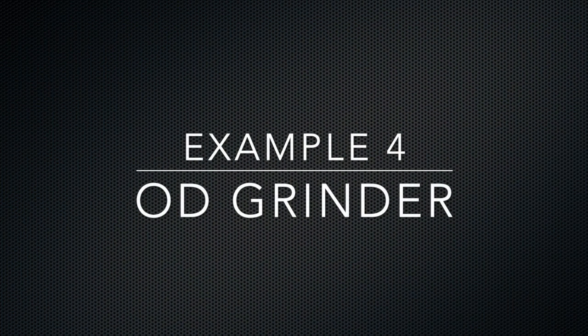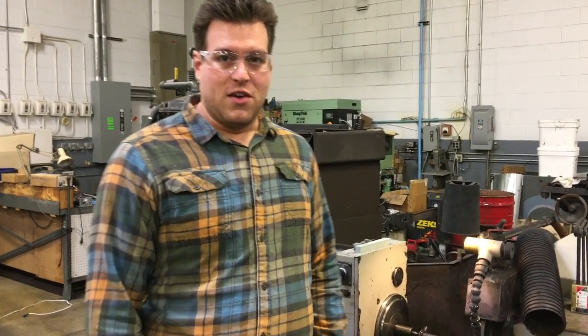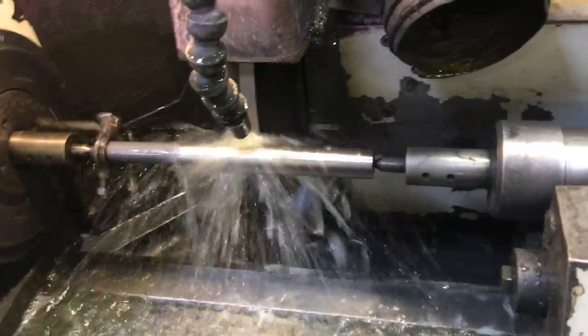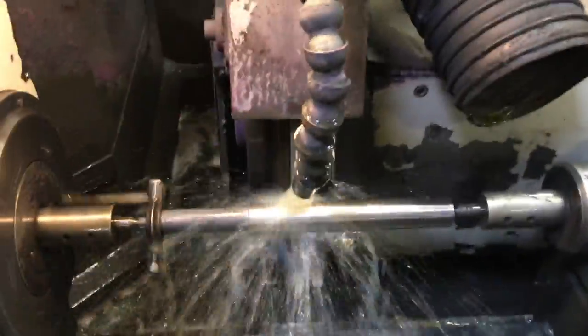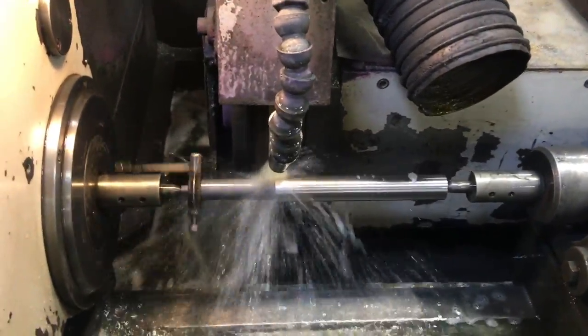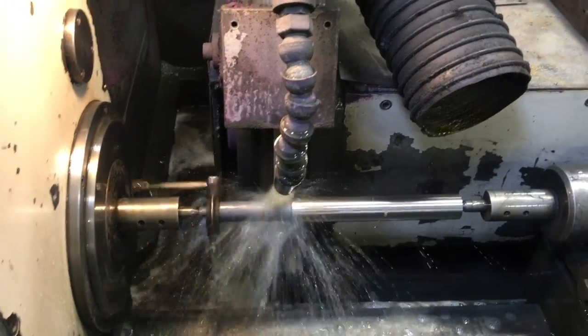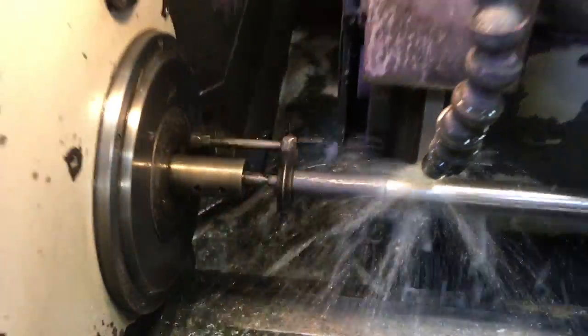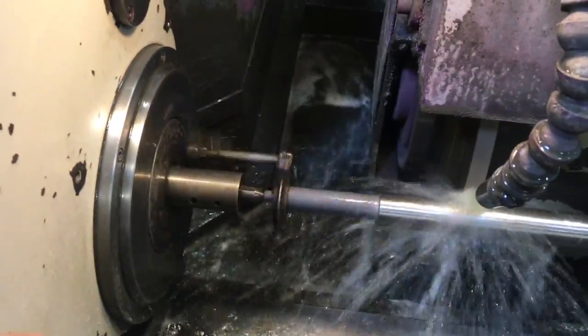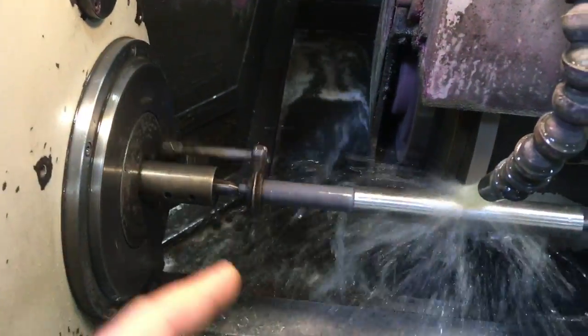Example 4, OD grinder. Hey, this is Andrew Stefanowski again. So this is another example of a grinding unit. This is an OD grinder. Basically, what's happening here is you've got a round workpiece that is held between centers. So there's a female center in the blank, and then these are male centers. This is called a dog, and this is actually clamped onto the material and being rotated here by the machine.